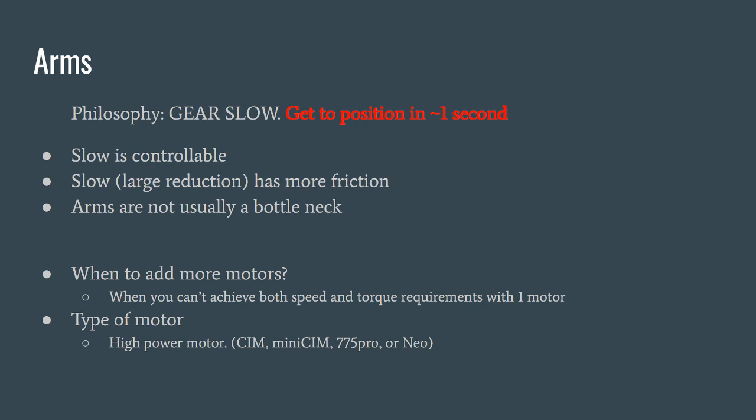Neos are stronger than Sims. Yeah, that's true. So generally, there's closed motors and there's open motors. Sims and mini Sims and bag motors are closed motors. They're generally heavier. They basically have a heatsink built in. So they have a lot of metal to hold a lot of heat, right? And they're generally much more robust.